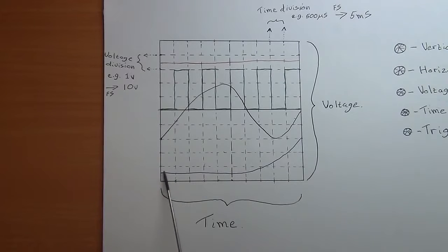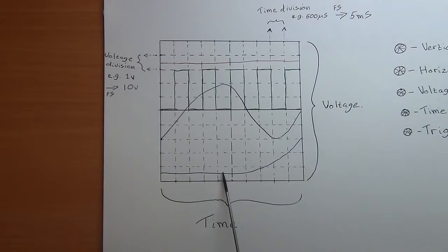Then over here, what I'm showing is, let's say we hook this up to a capacitor that was charging over time. As you connected the capacitor and had a battery or a variable power supply attached, if you set your time base slow enough, or even if things are happening fast, you might see a signal like this, where the charge voltage is initially low in your capacitor, and then it starts building up over time.